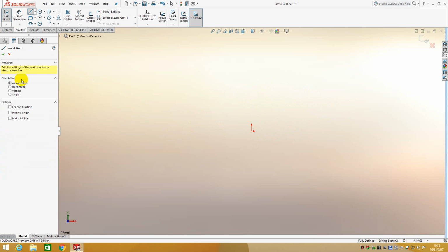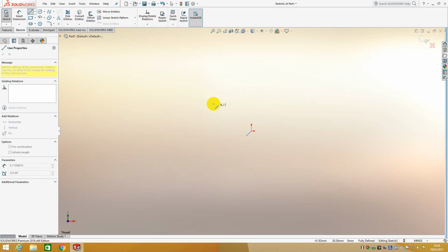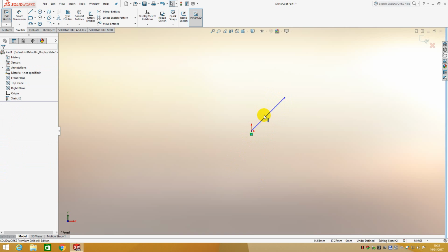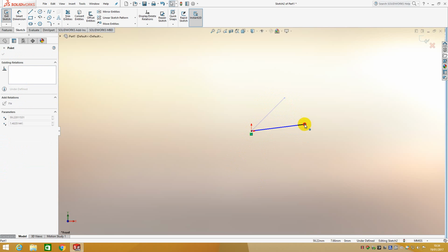Likewise there's a vertical option in there where you can lock it to vertical. There's an angle option as well, so say I wanted a 45-degree line, and drop that first point, and you can see it's just giving me 45 degrees from vertical here. It's taking vertical as 0 degrees and then round to there 45, but I can go in either direction. But it doesn't have a relation that will lock that to 45, so it's only as I'm defining it there that it's locked to 45. As soon as I've finished the line, I can drag it off 45.